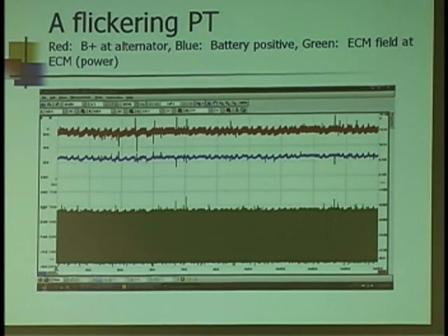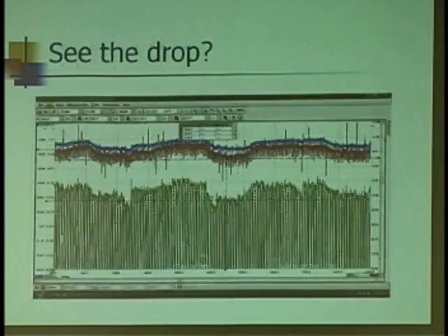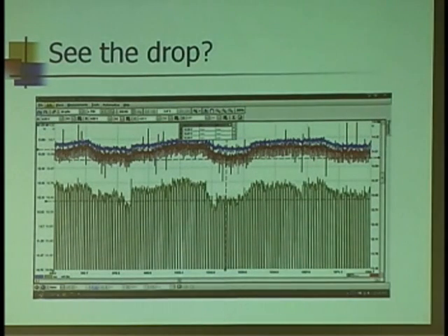Now again, I have a lot of time. This is almost 2 minutes on the screen. I'm going to zoom it in a little bit. And this scope allows me to manipulate each individual pattern. In other words, I can grab it and I can move it on the screen to lay it on top of another one, or I can eliminate the ones I don't want to look at and have just one showing, or any other thing I want to do with it. So that's what I did. I laid the 2 voltage signals on top of each other, and they look like they're matching pretty good.